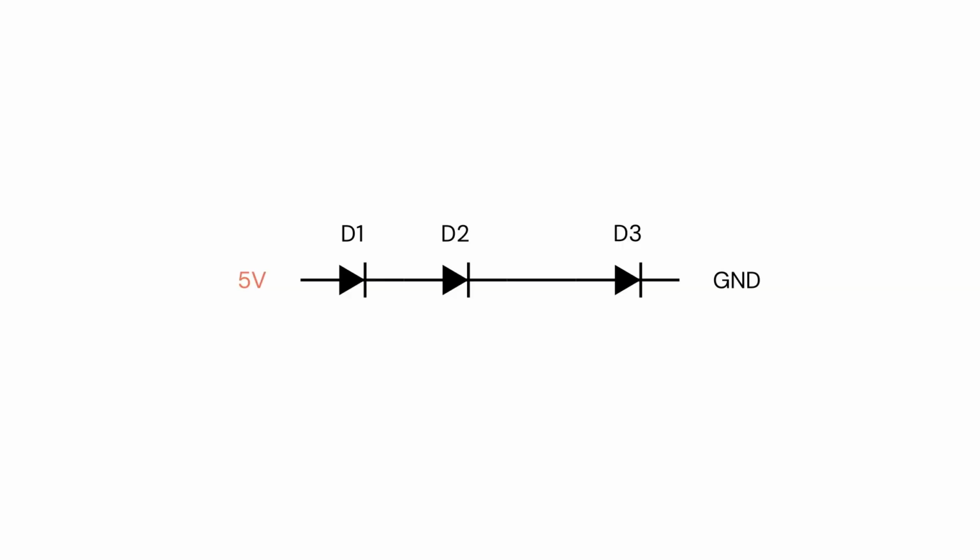A couple of tricks can help you analyze and design circuits involving diodes. First, ensure all currents are appropriately limited, as we just discussed. Then you can assume the forward voltage as a constant. If you're using silicon diodes with currents in the order of milliamps, which is quite typical in digital components, you can assume the forward voltage to be 0.7 volts.